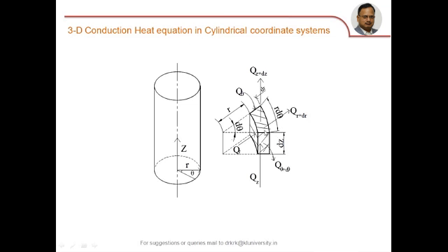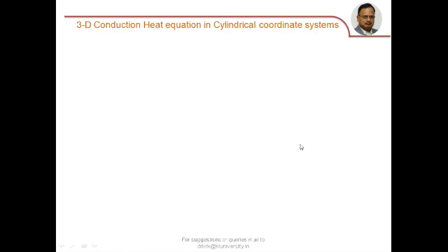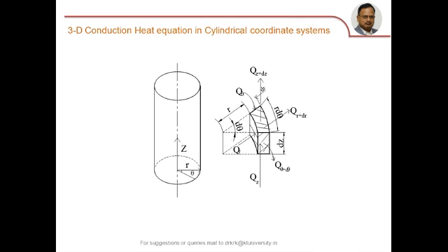So when you consider the internal generation of heat energy within this element, the energy balance equation can be written as: the energy entering the element plus energy generated within the element is equal to energy leaving the element plus energy stored in the element.